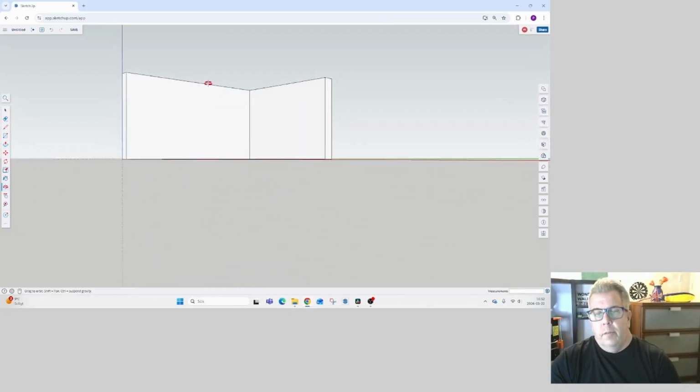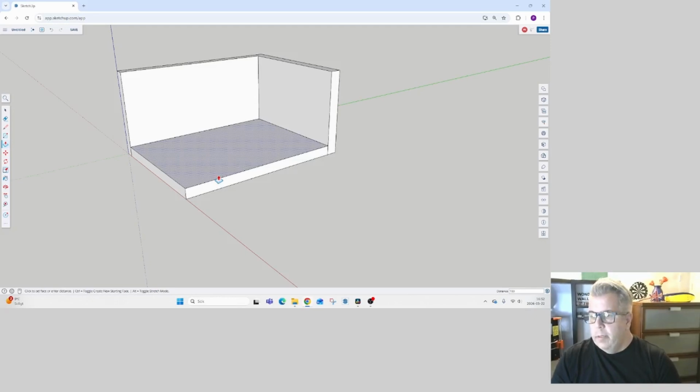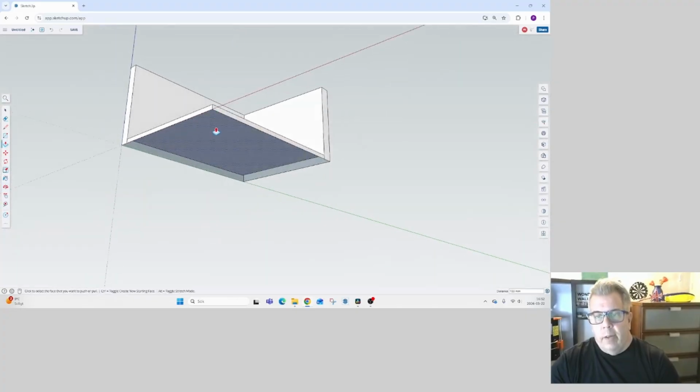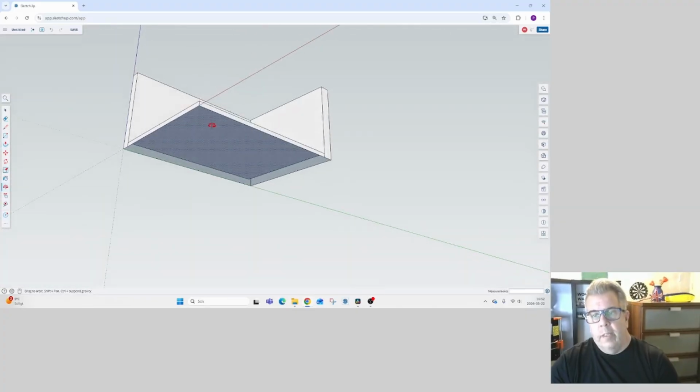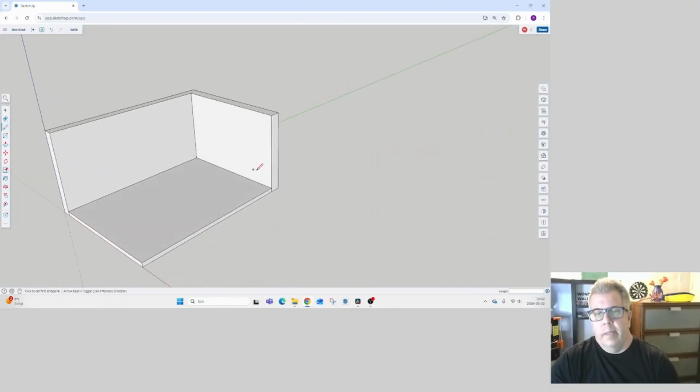And then we're going to give the floor a little thickness too. We can go up and yeah, 100 millimeters, fine, with enter. So created. Just to pan around, when I look underneath, you see it's taken away the surface. If this happens, it's just to activate the line tool and draw a new line on an existing line, like this, to create a new surface.